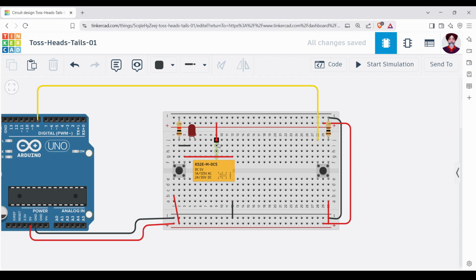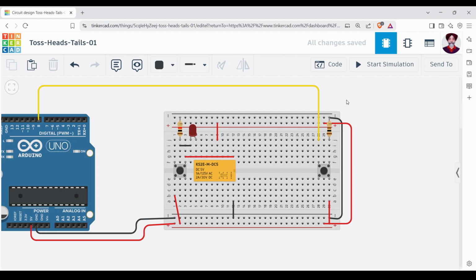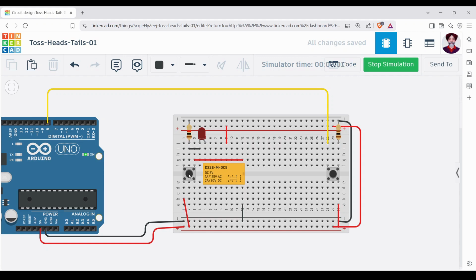So it is getting direct power on terminal number 4, which is the common, and the normally open should get switched on, and this LED should get switched on. Let's see if this works. So when I, yes, it is working. So this means when I press this switch, the coil gets armed, the normally open becomes closed, and this LED is switched on. So what we are going to do is we will remove this wire and bring the wire from there to this side as required by the program.